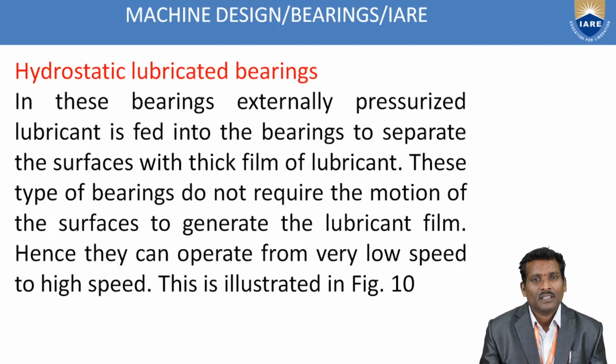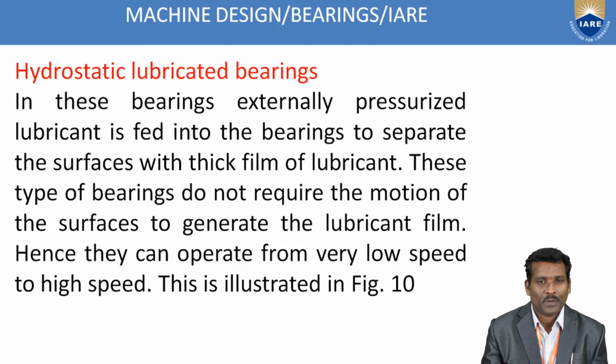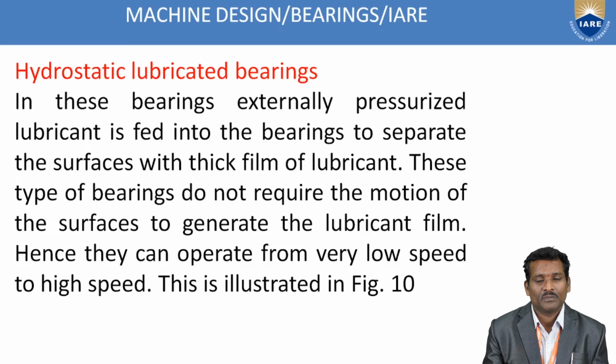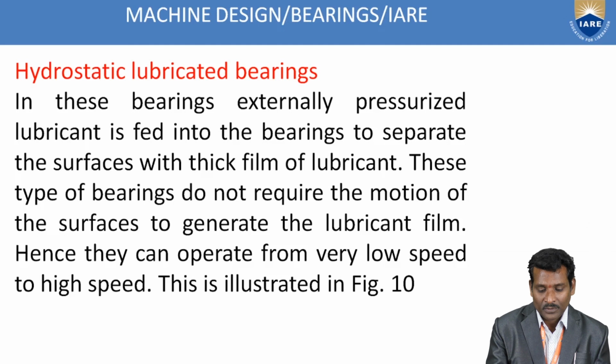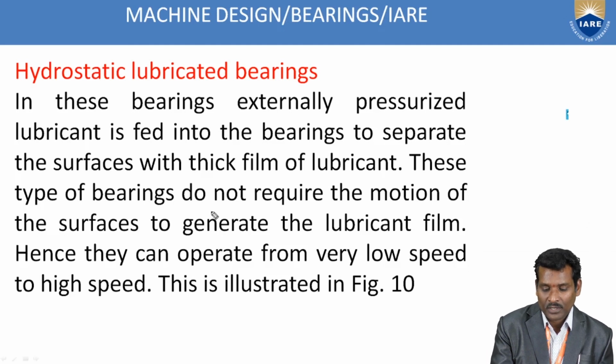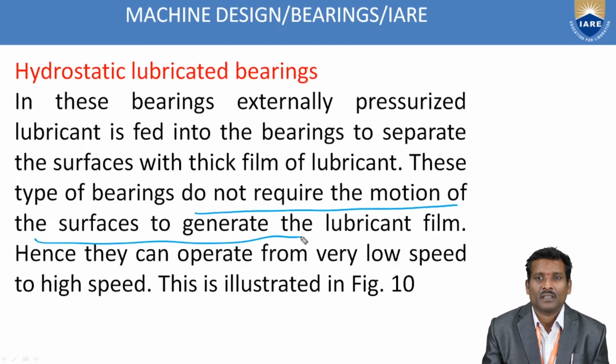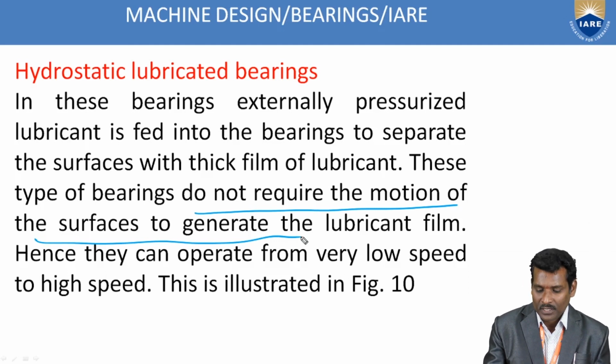But in this case, the journal need not rotate and no pressure needs to be built up inside the bearing, because we use external pressurized oil fed into the bearing. So we do not require motion of the surface to generate the lubricant film. That's why these bearings can operate from very low speed to high speed. As shown in the figure, the hydrostatic lubricated bearings.